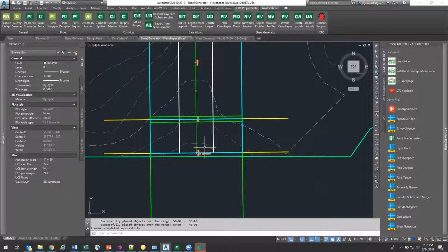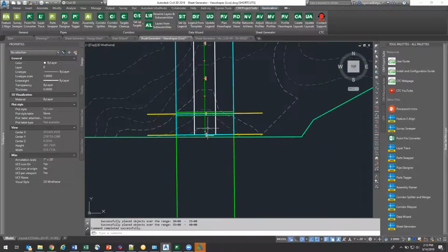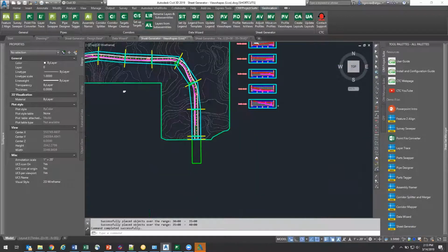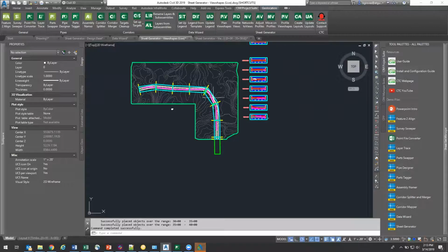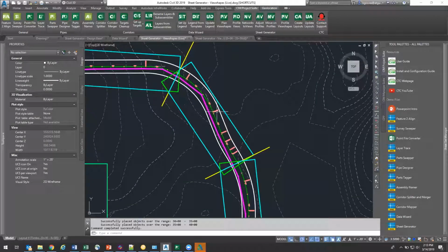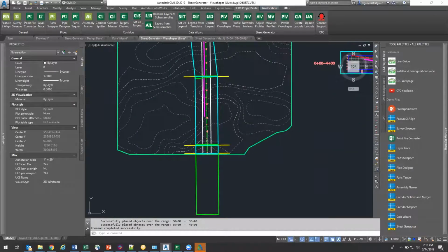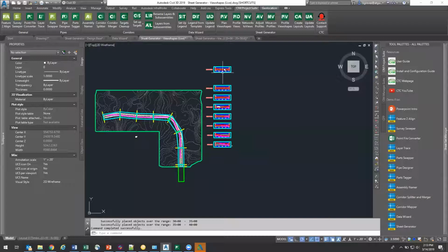I just want to show you that now our very last view frame has very little space inside of it that we're going to be plotting. We can't really make these all any longer or separate them out. We're already aliasing a little bit of this curve potentially up there in the north. So when I now go to profile views, I still have 1, 2, 3, 4, 5, 6, 7, 8 profile views. I have 1, 2, 3, 4, 5, 6, 7, 8 plan shapes. These profile views are going to talk to the rest of these objects, and they're going to update.